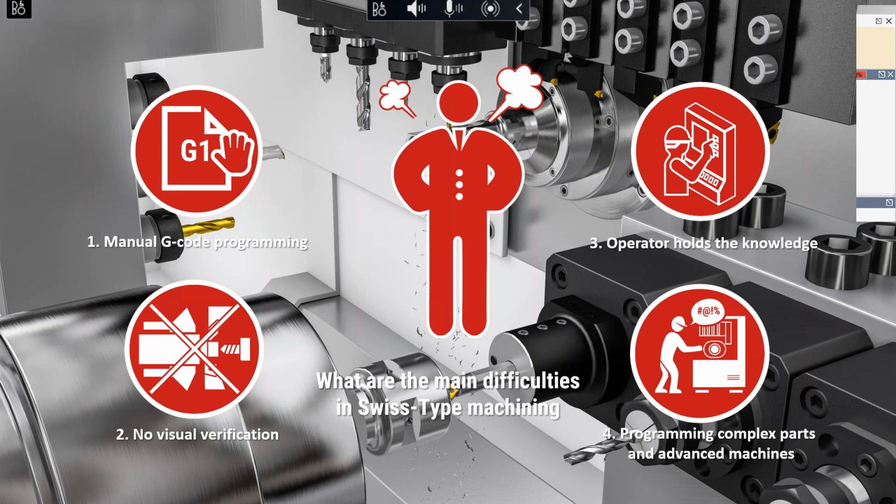Just imagine if you are in a workshop with, let's say, 5 different machine brands, maybe different kinematics, and you cannot have only one person who can remember all those machines, M codes, and G codes. The best way is actually to store it in the CAM software, and you just need to select the machine and generate a G code for that, right? So this is one of the main problems, that the experience actually goes with the operator. Yes, so I found that the CAM, in this case, is very much needed.